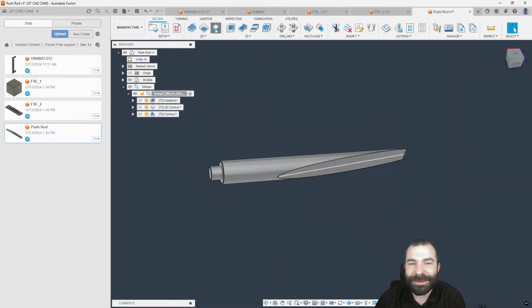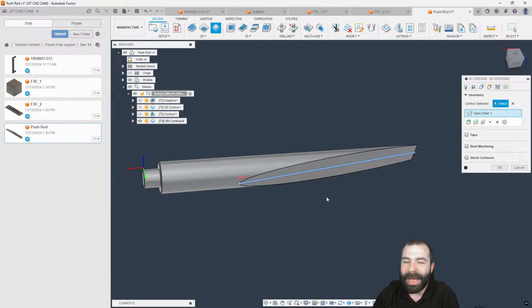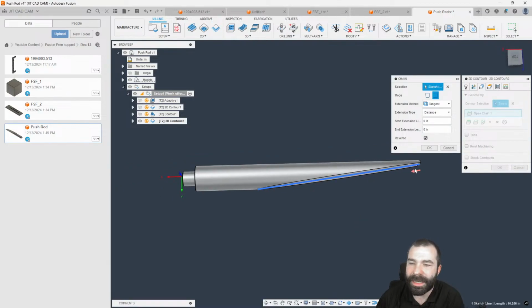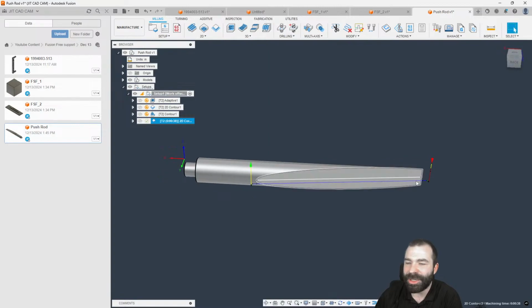But if I wanted to do a 2D contour, as you can see, it's giving me that silhouette profile I just created. I'm holding the Alt key to give it one edge. Again, we're going to reverse direction, so our red arrow is outside, maybe extend it off our part, whatever our distance is. And we could change our Z heights, but this is another way to completely cheat the system, right? It's all these little workarounds I think you guys absolutely love seeing.